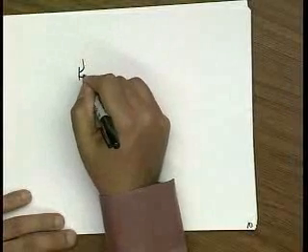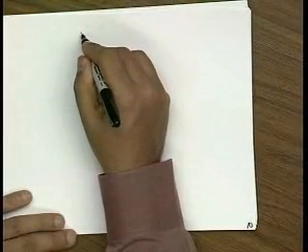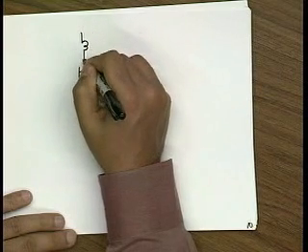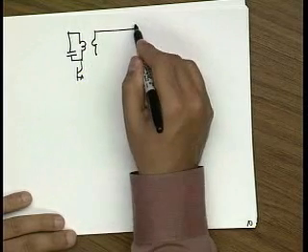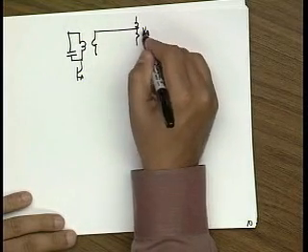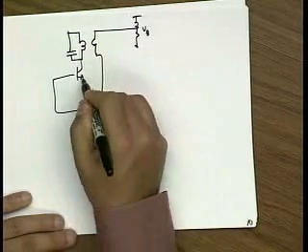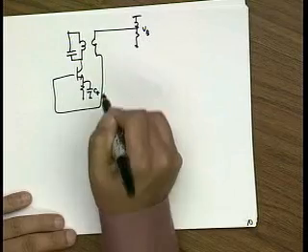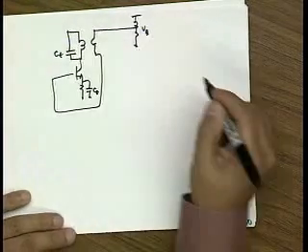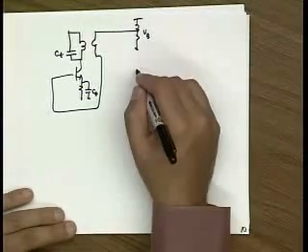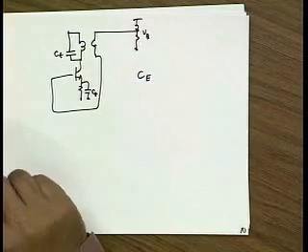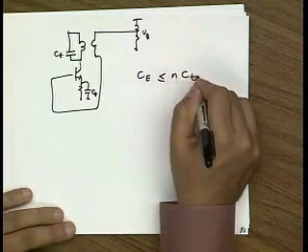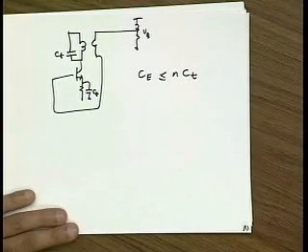All right, so if we go back to our full schematic, it looks something like this. I'm going to have a transformer winding here, a bias voltage here, and an emitter capacitance here. There's one important practical thing you need to be aware of. You need to make sure that this emitter capacitance is less than N times the tank capacitance. Okay? And that's to avoid